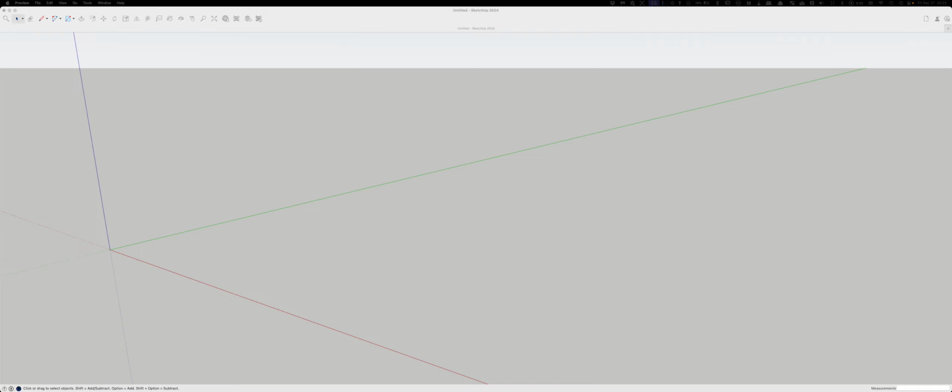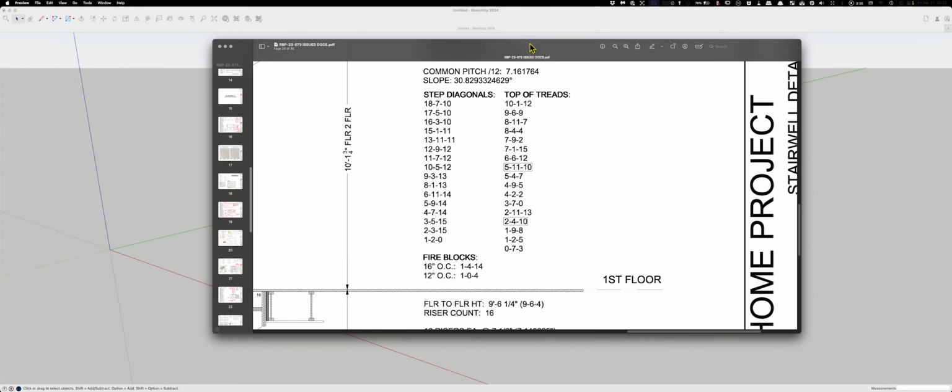So what I'm going to do, I'm going to make these stairs 3'6" wide. And if you'll notice, I went through and I put a square around where my landings are. So the top of treads or finished framing or whatever, that's this number right here. So that's the top of the subfloor on this landing and on this landing.